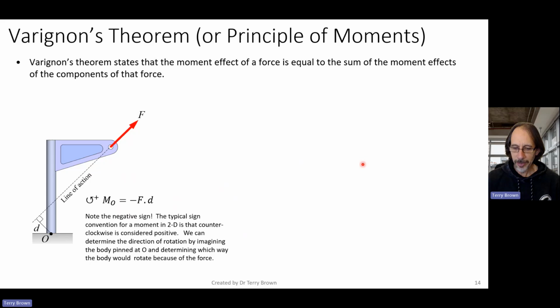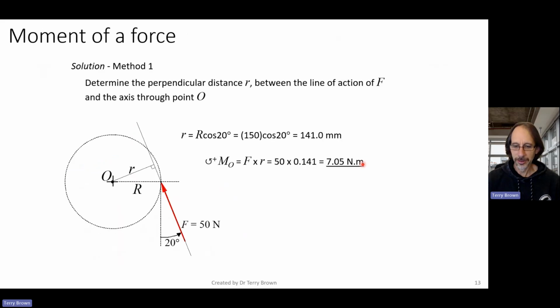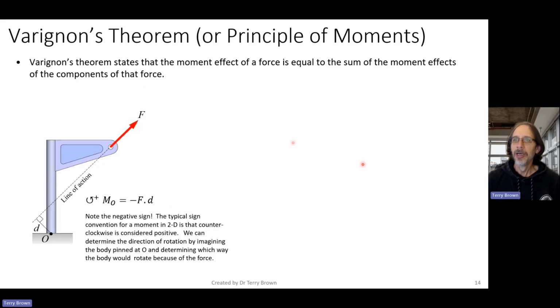Some of you may already know about this and been thinking, well, why didn't you do it a different way to what I've just done? And that is to use Varignon's theorem, or what it's also known as, the principle of moments. So Varignon's theorem states that the moment effect of a force is equal to the sum of the moment effects of the components of that force.